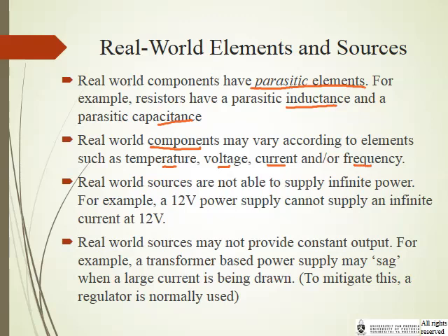the frequency. The resistors that you're going to use in your practical, for instance, are called 5% resistors. So that resistance can vary plus minus 5% in terms of what the actual value is, but also as the resistor gets hotter, the resistance goes up. As the temperature cools for a resistor, the resistance will drop. So it can be temperature dependent.